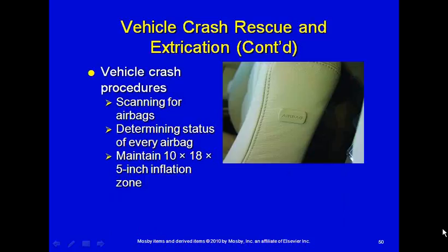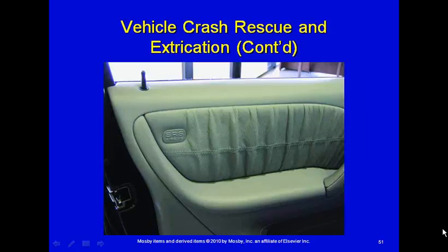Look around for indications that there are side airbags, knee airbags, pillar airbags. We're looking for a tag, like on the seat, that says airbag, or a tag that says SRS, which would indicate an airbag as well.